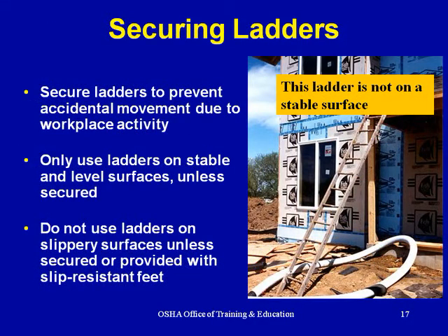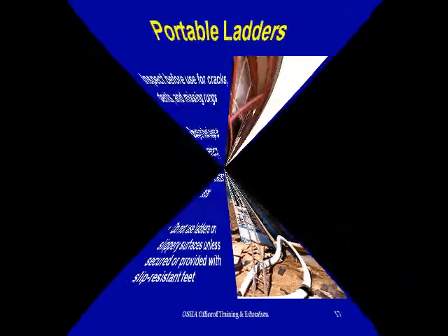Securing ladders. Secure ladders to prevent accidental movement due to workplace activity. Only use ladders on stable and level surfaces unless secured. Do not use ladders on slippery surfaces unless secured or provided with slip-resistant feet. This ladder is not on a stable surface.